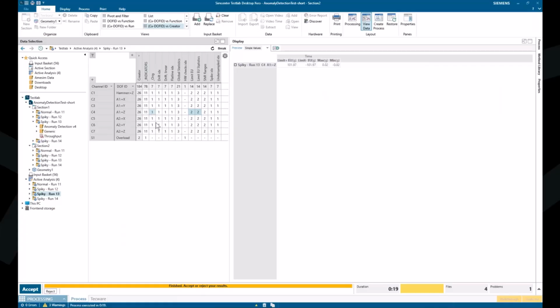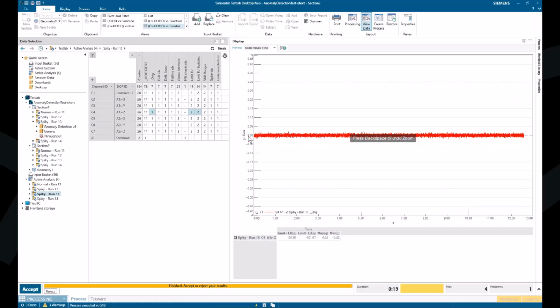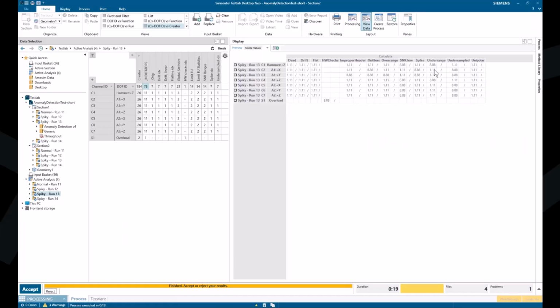You can show the signal here. So that's the signal, and let's see what happens if I change the scaling to plus minus 9. And you see it's basically a flat line. So it's really questionable whether either the limit EU is wrong or the measurement maybe didn't pick up what you thought it picks up. Again, this can be done on many of the channels. Maybe check which one was reported also.